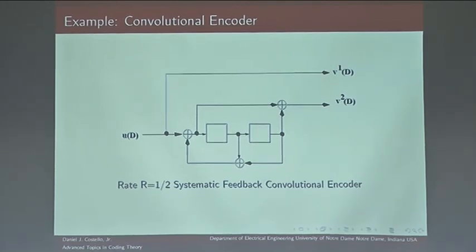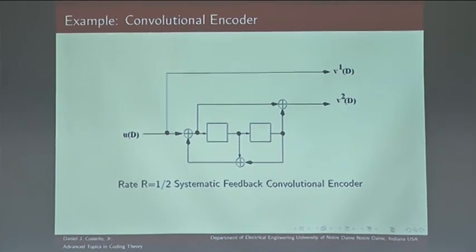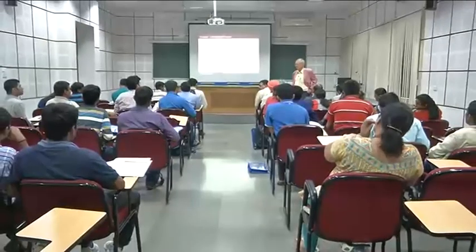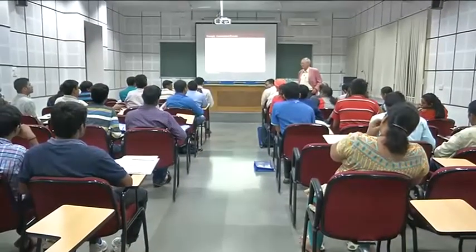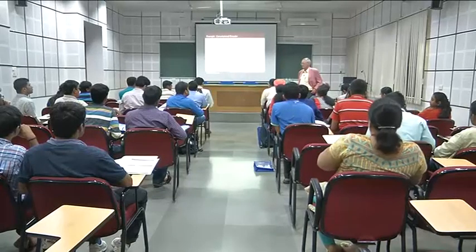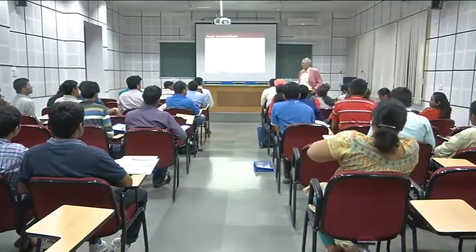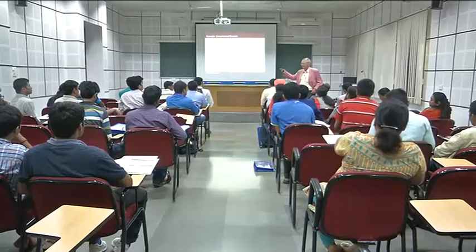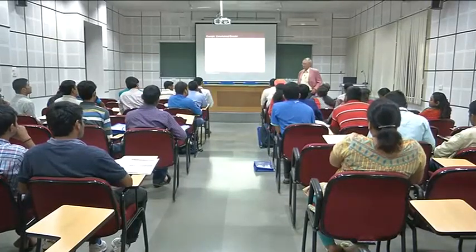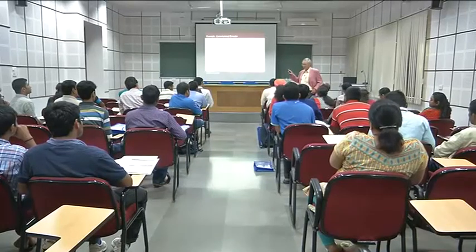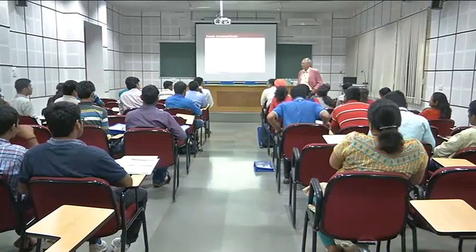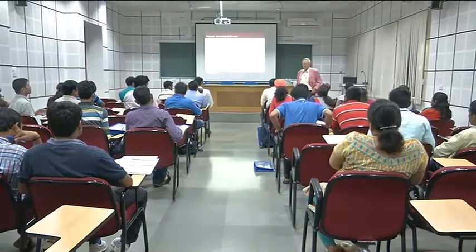This feedback convolutional encoder resembles an IIR filter structure. So I was thinking there may be stability issues, but since the arithmetic is modular, there might not be any. There's no stability issues in the encoding, but it is an IIR encoder. And there are some consequences to that, which in the very next class we'll discuss a little bit. Any other question on this?